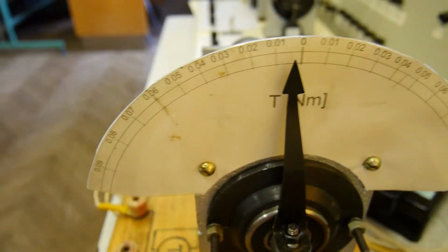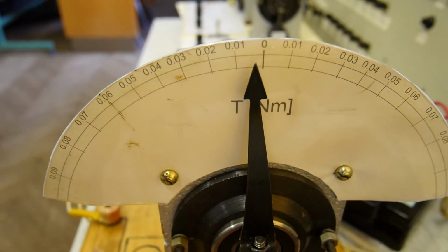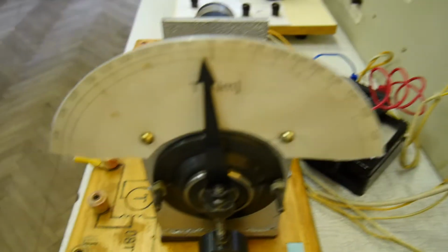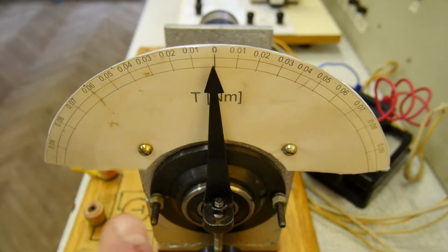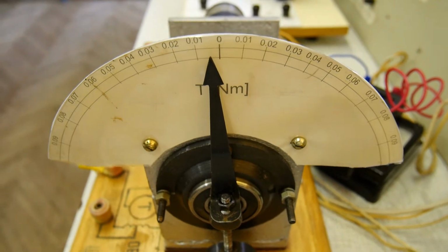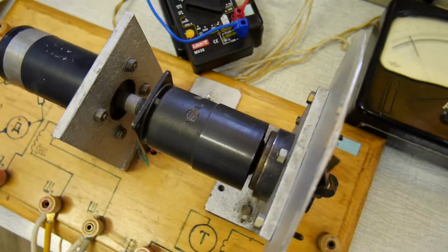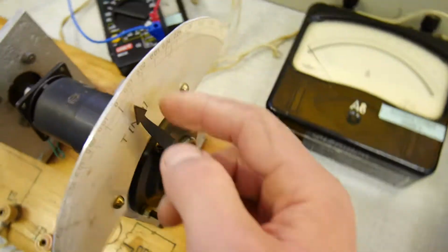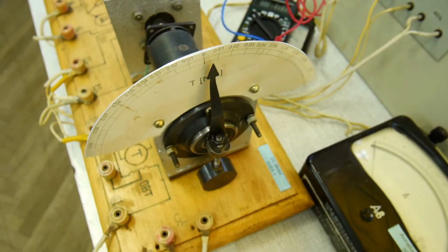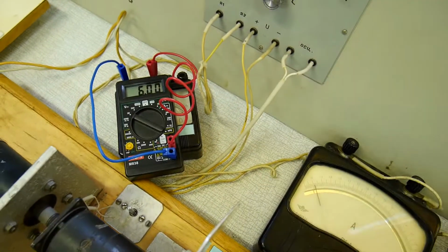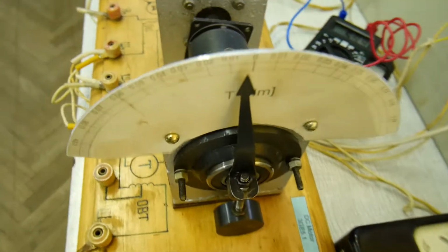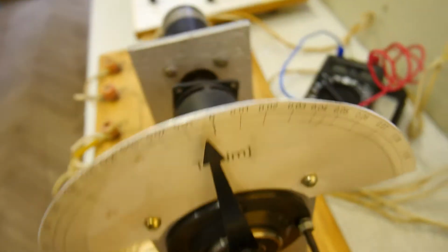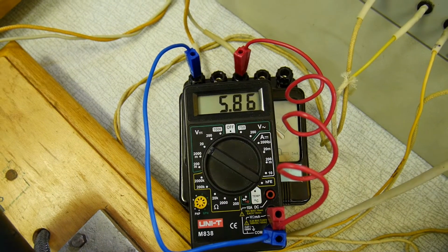As you can see, we got almost zero torque, almost zero but not zero. This is because if I disable power, you will see, this is the zero. But now, due to friction in the ball bearings in the brake, we got some small torque, but this small torque is also noticeable. Okay. So, exactly right now, we got a braking torque of less than 0.01 Newton meter, and the speed is 5,800.